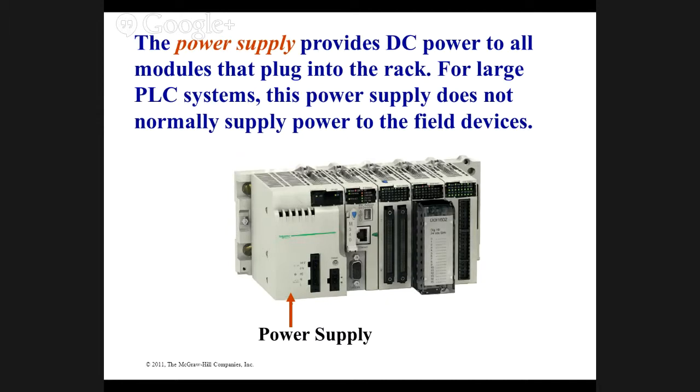You can swap it to any slot if you change the program. The processor must remain in slot 0. It's just one of the rules in an SLC system. The new ones, it doesn't matter, but in the old gray ones, the SLC, it does. It has to go in slot 0.